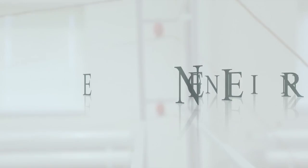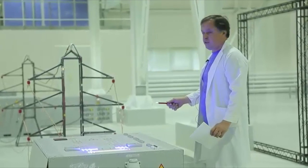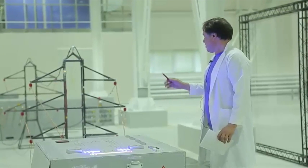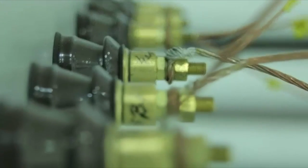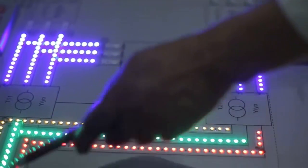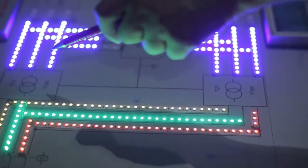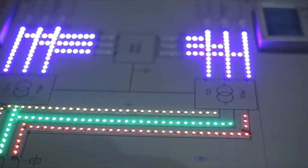Here we have a model of a 3-phase, 2-circuit, 22 km long power transmission line. The model consists of a transformer substation and power with 6 lines. We have 2 transformers in the substation, main and backup, energized either from a single or from 2 individual lines. In this particular case, the 2 transformers, main and backup, are energized from a single line.